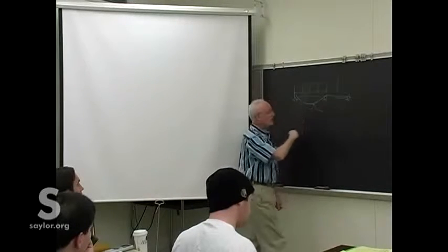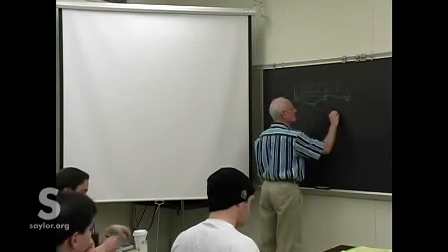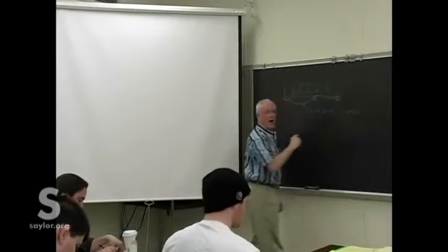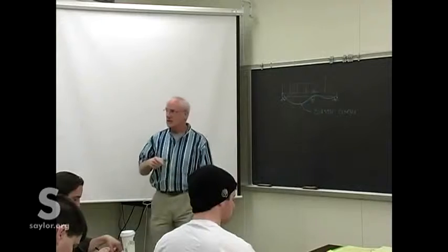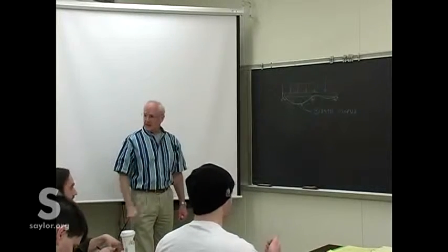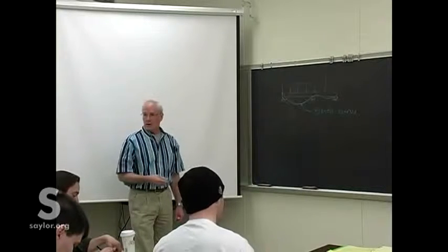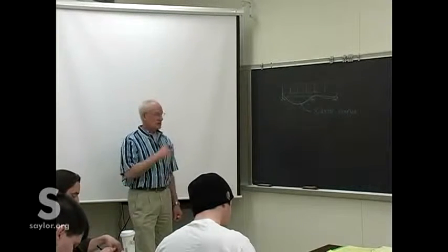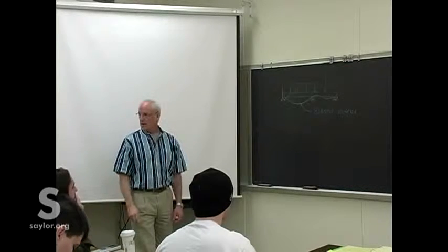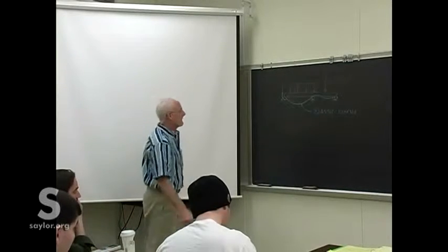What we're going to do today is come up with the equation for the curve of the beam when loaded. It's known as the elastic curve because all the materials in this class are considered elastic. They bend predictably. For the most part, in the design considerations we make, they return to their original state when unloaded.